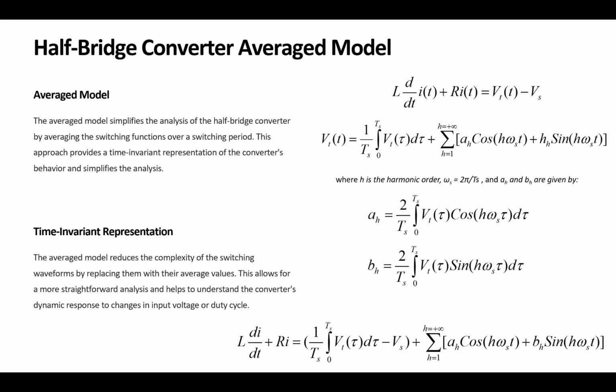So in a high power demand, like in a transmission grid or an industrial scale, multi-level has better characteristics, and it's more popular for being adopted for the configuration. So this is one way we could decide between the normal single phase, single level, or full bridge versus multi-level.